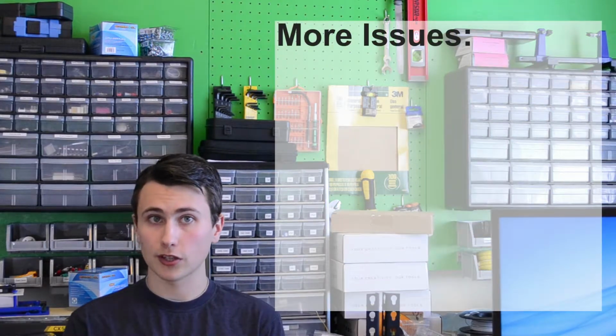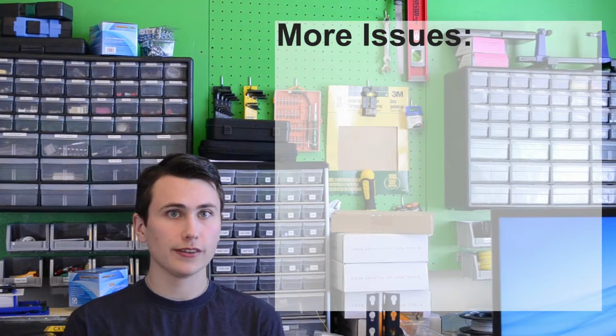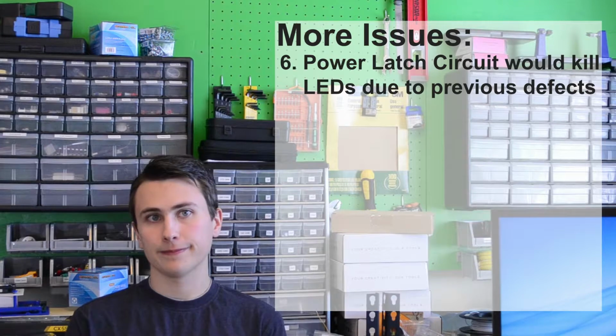In the first iteration of the design, I also implemented a power latch circuit, which would provide a means for the microcontroller to disable power to itself, and a hardware button to enable the power and latch it on. If one were to have actually used this functionality, then the 5 volt rail would have latched off and we would have cooked all of the LEDs on the board due to the previous two design defects.